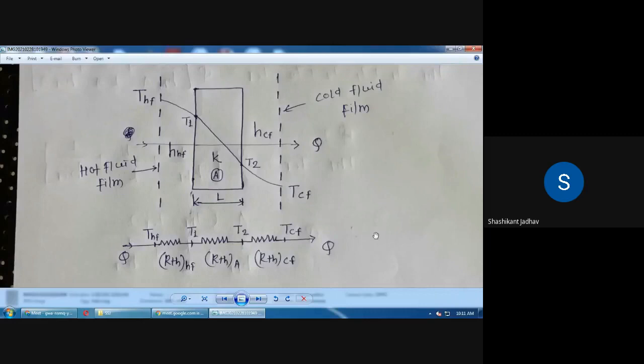Shinde, can you tell? So what is the standard equation for the plane wall? We have derived the equation for the heat conducted through the plane wall. So according to that equation, tell me what is the heat transfer rate through this plane wall. A similar plane wall is there, the same temperature difference is there. So what is the equation for that? Minus K into A into delta T by delta X or delta L. Okay, so this is Fourier's law of heat conduction.